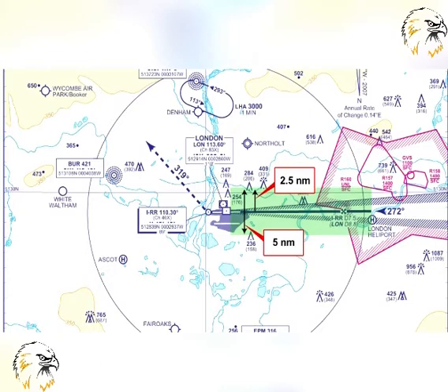From an operational point of view, the obstacle clearance applied in the development of each instrument approach or departure procedure is considered to be the minimum required for an acceptable level of safety in operations. Operators usually apply higher criteria than this, thus resulting in aerodrome operating minima for commercial air transport operations.